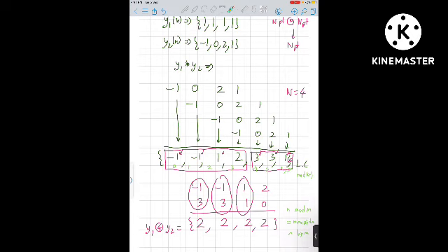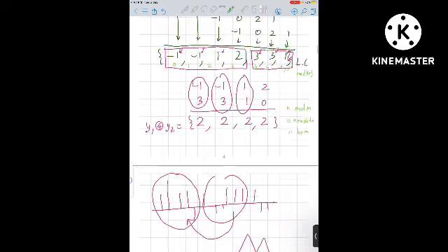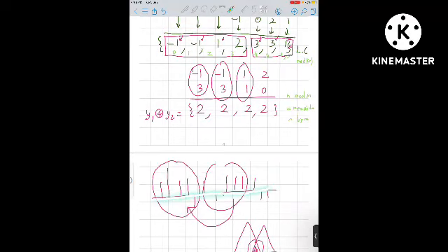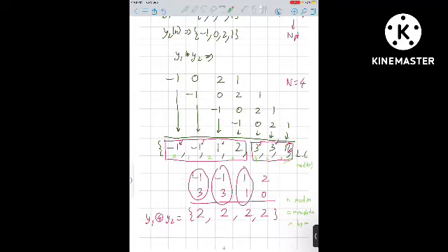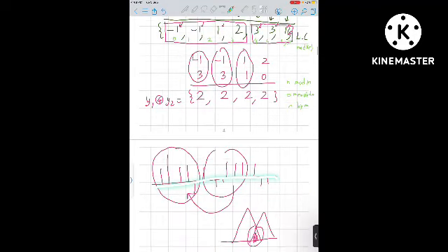Actually what happens is that it is not that I take, it is the mechanism of circular convolution. So what circular convolution is doing is that it convolves an N-point sequence with another N-point sequence, and the resultant has to be N-point. In reality, when you have a long sequence, something like this, what convolution does is that it actually aliases this. Just like in the frequency domain you had aliasing, similarly in the time domain.